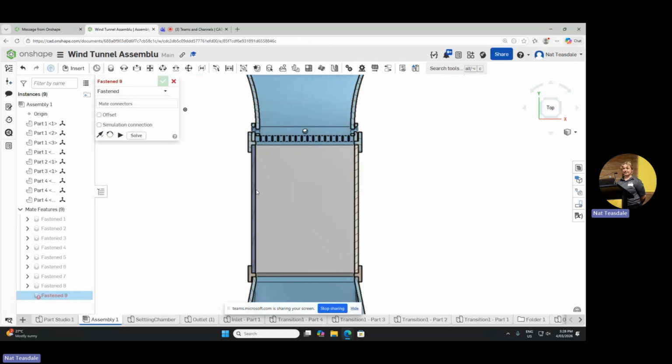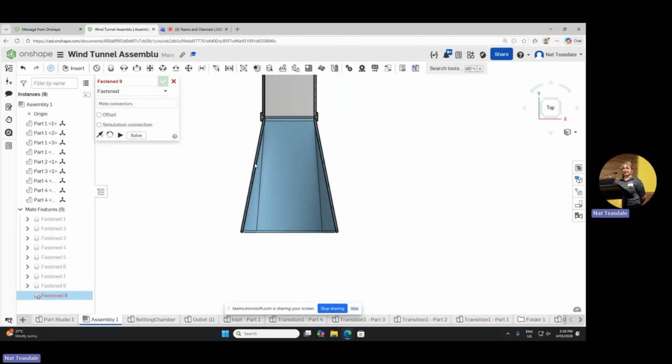It's the same with the outlet here. So if we look at the outlet right now, this outlet could have technically been shorter, it could have technically been longer, but what we wanted to do with this outlet is essentially decrease airflow by changing the size of the hole first at the inlet and the outlet of the outlet, and then also adjust the geometry to fit. So we have to always be considering how airflow is going around these things. It's fun.